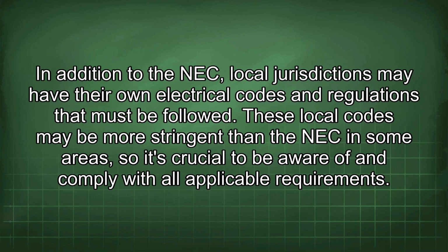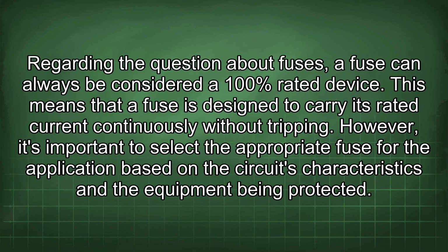In addition to the NEC, local jurisdictions may have their own electrical codes and regulations that must be followed. These local codes may be more stringent than the NEC in some areas, so it's crucial to be aware of and comply with all applicable requirements. Regarding the question about fuses, a fuse can always be considered a 100% rated device. This means that a fuse is designed to carry its rated current continuously without tripping.